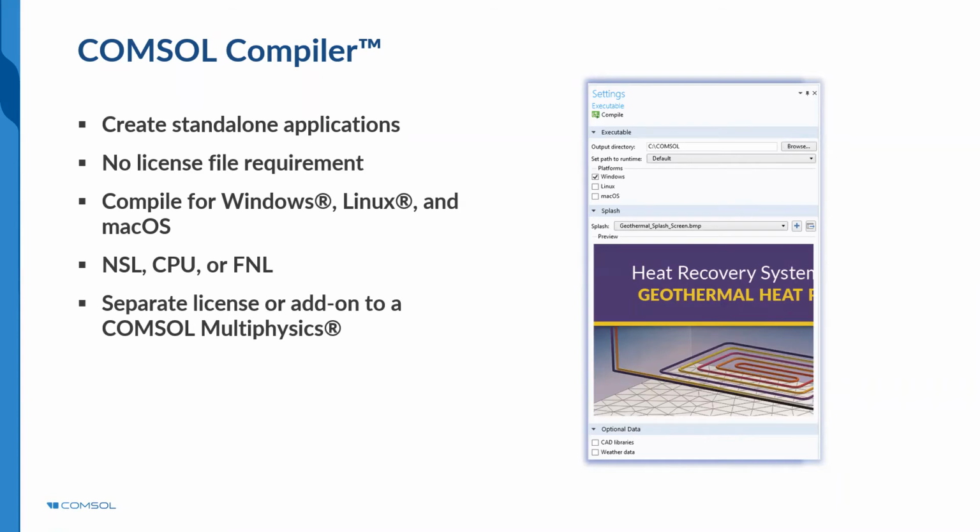COMSOL Compiler: there are various ways of using an app. One of them is creating standalone apps. That can be done using COMSOL Compiler. Once you do that, they become an .exe file. Then there is no license file requirement of COMSOL, and you can compile on Windows, Linux, and Mac OS.